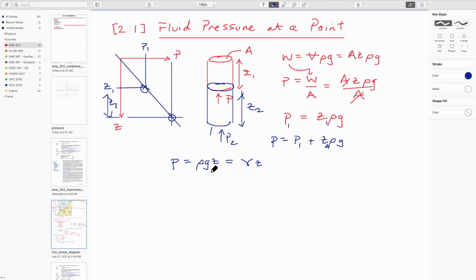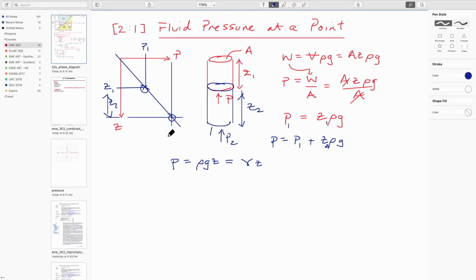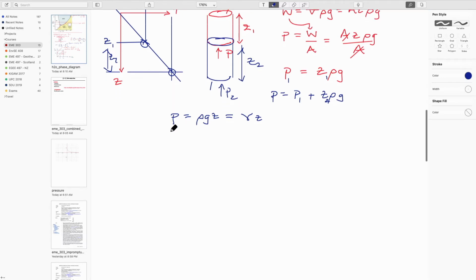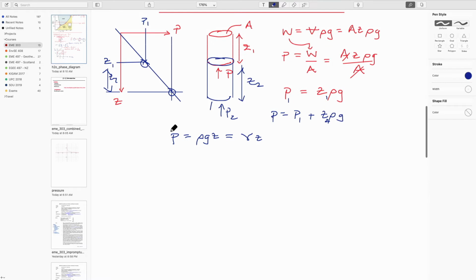And you know that, right? As you go down in a swimming pool, the pressure initially at the top we take as 0, because this is gauge pressure. And as you go down into the water, it will increase linearly. And at some stage, at 14 feet in a diving pool, it might even hurt your ears. So that's the easiest way for us to think about it.